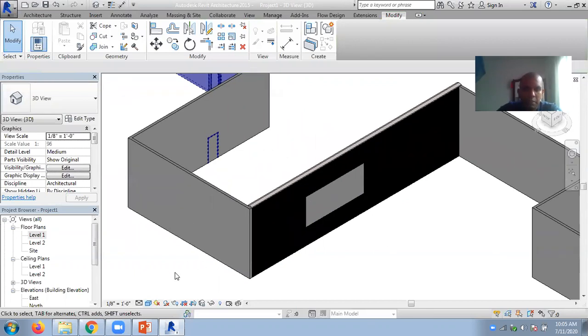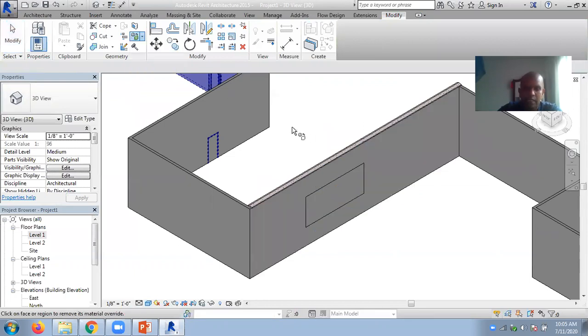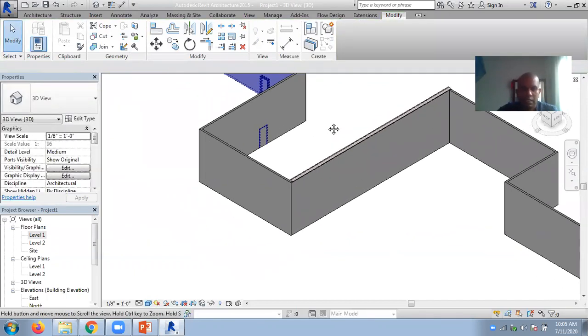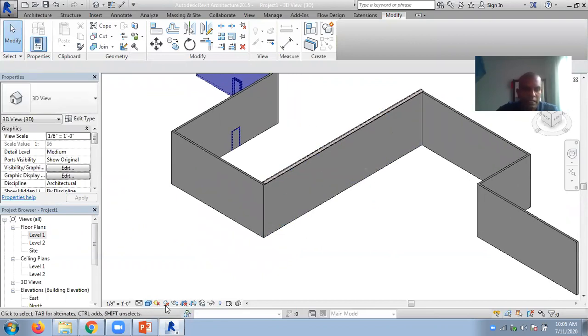And if you want to remove the paint, there's a tool called remove paint here. Just select this area and remove. And if you want to remove this split, just select this and press the delete key. It will be unsplit. Okay. So I discussed this split face tool as well as the paint tool, applying paint and removing paint, and the demolish tool. Any problems with these three? Please tell me. I'll give you 2 minutes to practice. Just tell me if you have any questions.